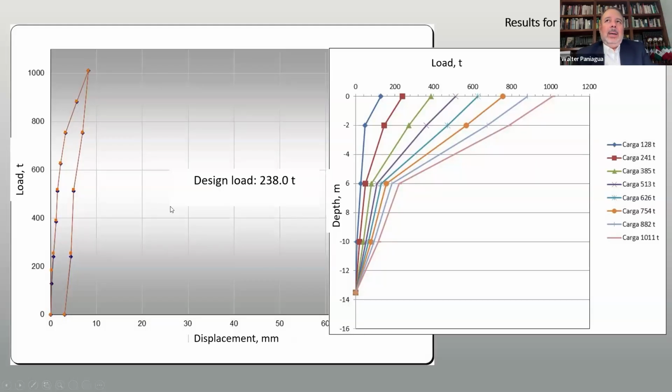So I want to make a reflection on this. If we assume that we can develop all the end-bearing capacity, we will have a large displacement. So that will not be allowable by any structural or any common sense engineer. So you want to live with friction only.